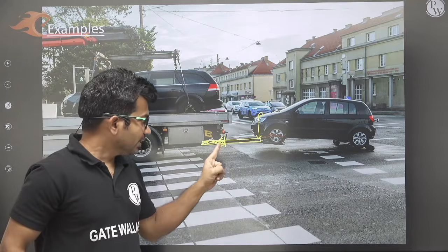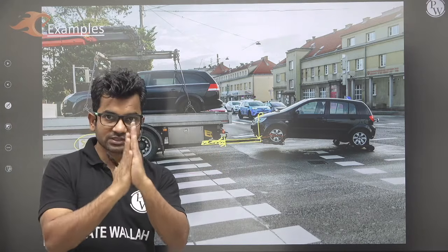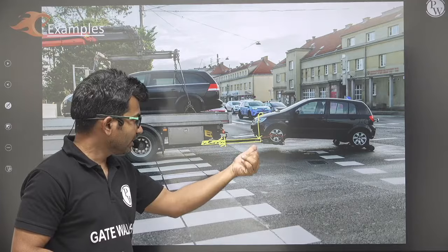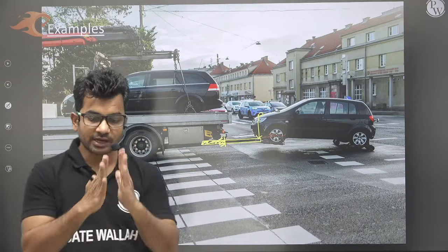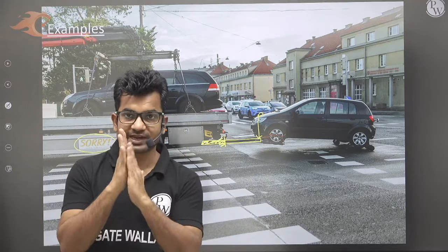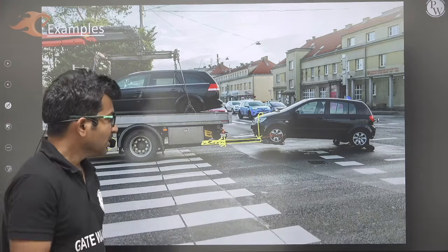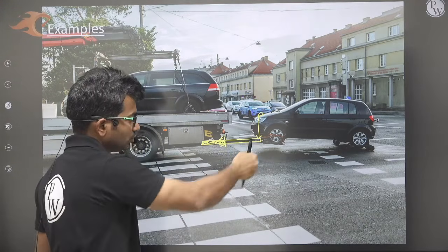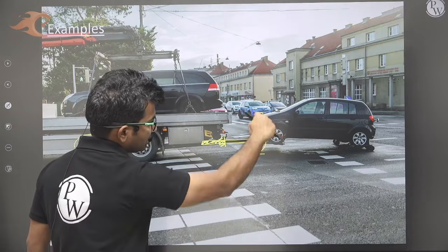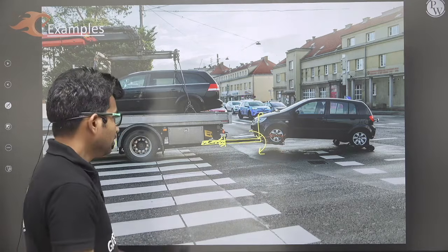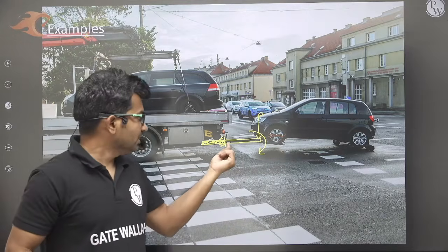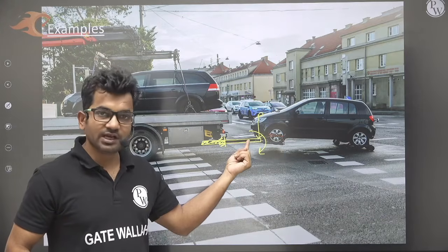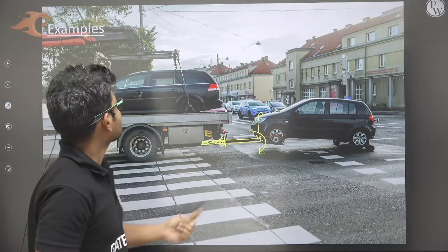So in this part we will be having some shearing stresses also. This P load is acting parallel to the section. So all these are cross sections, and P load will be causing sliding parallel to the cross section, and this will be causing some bending also here. Because of this, some bending will occur. So bending moment will occur, and bending moment will cause normal stresses. So in this part we will be having shear as well as bending stresses.